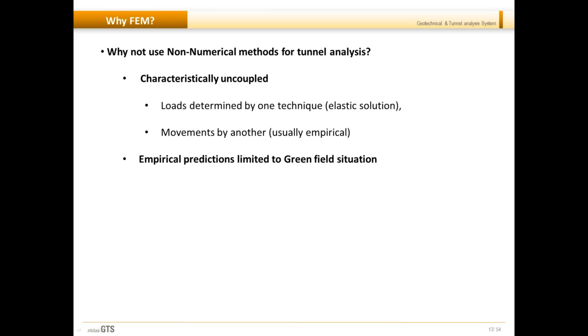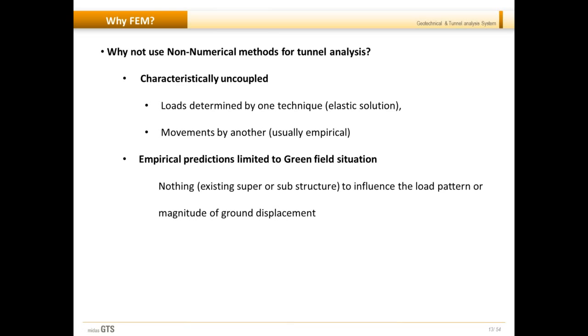Then another major limitation with these non-numerical methods is that their empirical predictions are limited to greenfield solutions. This means that they completely ignore any kind of load pattern that could possibly affect the tunnel excavation. So they assume that there is nothing existing other than the tunnel itself.